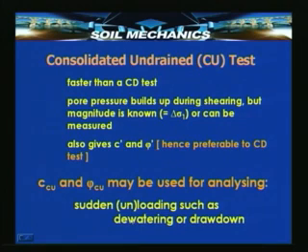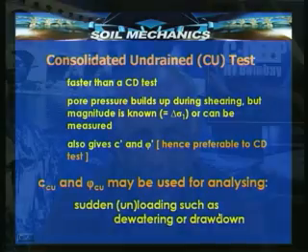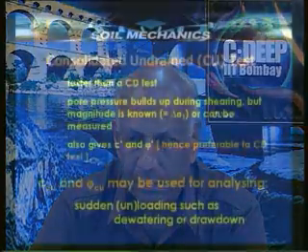Where do we apply this test? This test is good for situations where an embankment, for example, has spent a little bit of its life and now it is undergoing a sudden unloading. In such a case, CCU or phi CU will apply. Examples are dewatering and sudden drawdown.